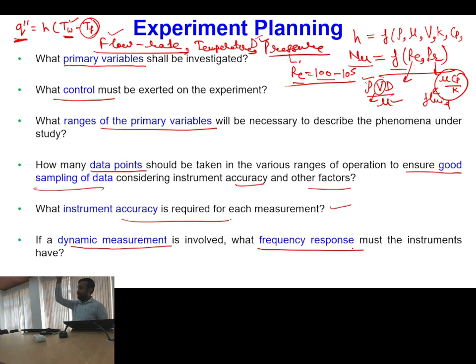Even if you have simply changed the interface of the data acquisition system, and you have mentioned that it should give output of 10 samples per second, it will give you 10 samples per second, but it may give all the 10 readings as the same value, because it is not able to respond to the input it is receiving from the instrument. So whatever sampling frequency you are considering for the instrument, the same should be applicable for the data acquisition system.